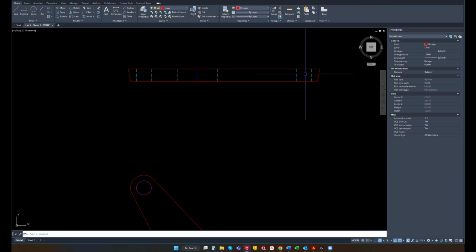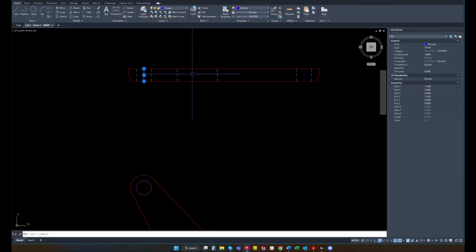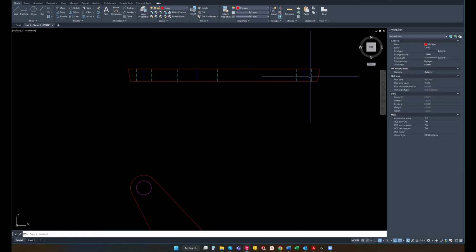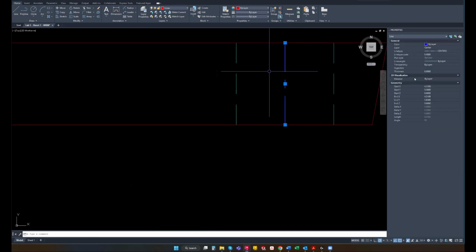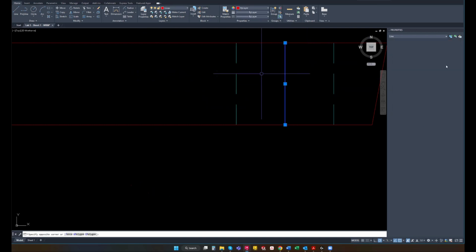So our hidden lines are showing up nicely, but our center lines are not. So I'm going to keep our global line type scale, which is what we just changed, at 0.5. And then I'm going to further reduce the center line type scale. So let's try like 0.4. And 0.4 looks like it works. 0.5, if I remember when I was practicing this, will not, but 0.4 does in fact work.